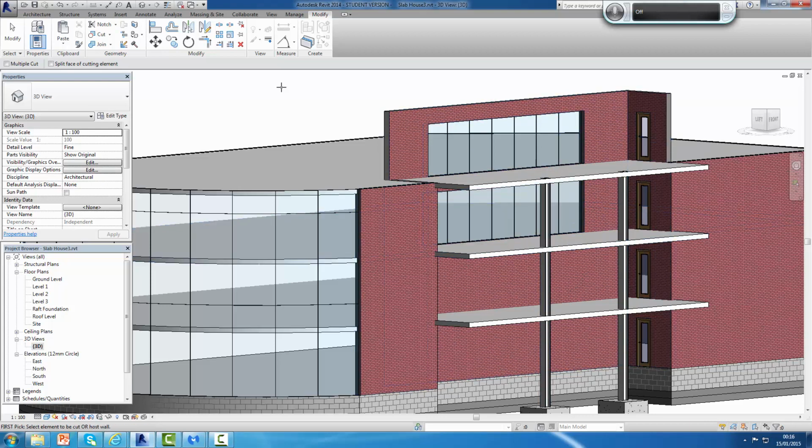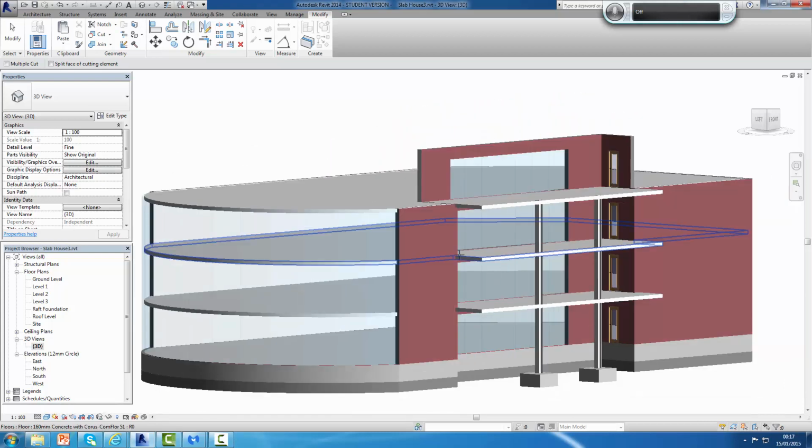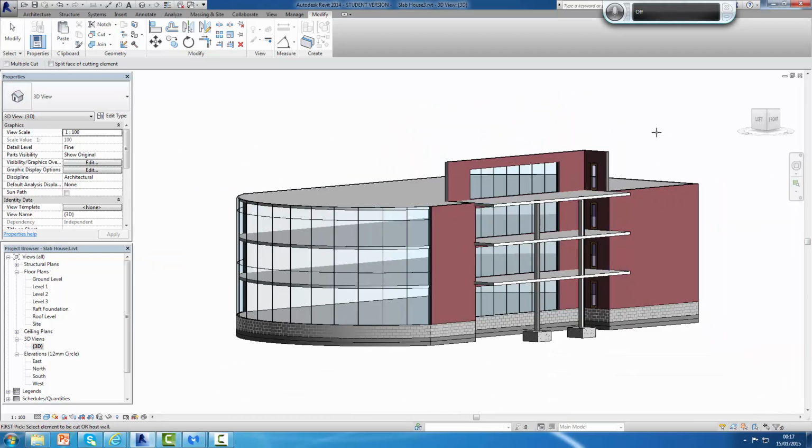Okay, so I'm going to go back into cut, pick that wall and carefully go back in until it highlights that particular wall. If you can see me moving my mouse from left to right and picking that wall, as you can see it clearly cuts that particular wall away. So I'm going to click again on cut, and pick the wall that I'm going to cut from, try and pick the actual wall that I've got, and that's where I've got that particular finish in there now.